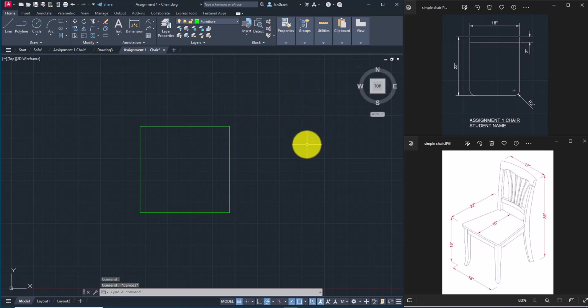Okay, so I use the escape key. That's another thing I wanted to show you, that when you start a command, any command, you see how it started here. If you click on the button at the top left corner called ESC or escape a couple times, you see how it cancels it out. So your main thing to look at right down here is the command line where it says type a command. It's just ready for you to enter something.